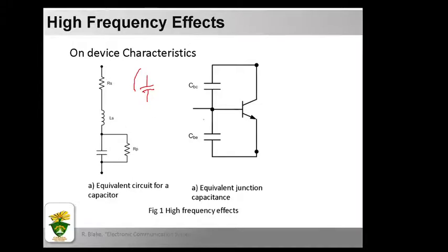Meanwhile, the capacitive reactance of the component decreases with increasing frequency. Eventually, a point will be reached where the two reactances are equal and the capacitor becomes a series resonant circuit. This point is called the self-resonant frequency, where the two reactances are equal.